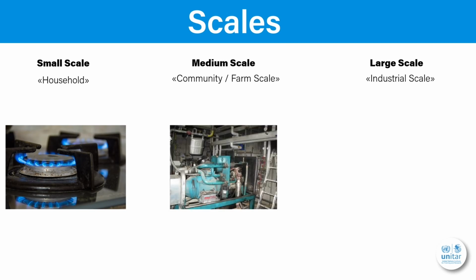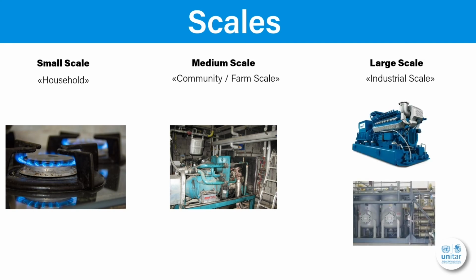On farm-scale systems, we already produce enough biogas to run a specialized engine with a generator producing electricity. If we also make use of the heat generated during the combustion of the biogas in the engine, we can use most of the energy contained in the biogas. At large-scale systems, the size of the biogas engine increases to produce more electricity and heat. The heat is often used partially to heat the digesters, especially if they are operated under thermophilic conditions.